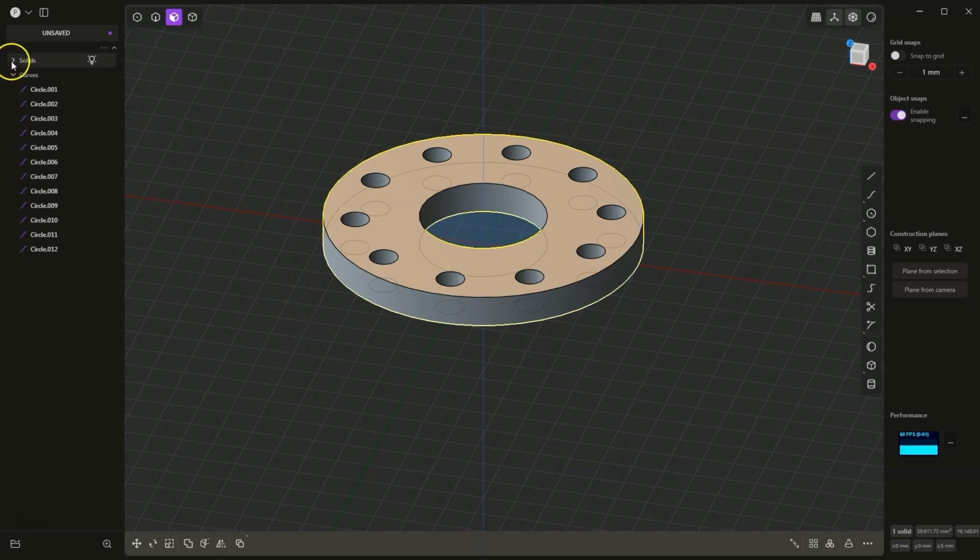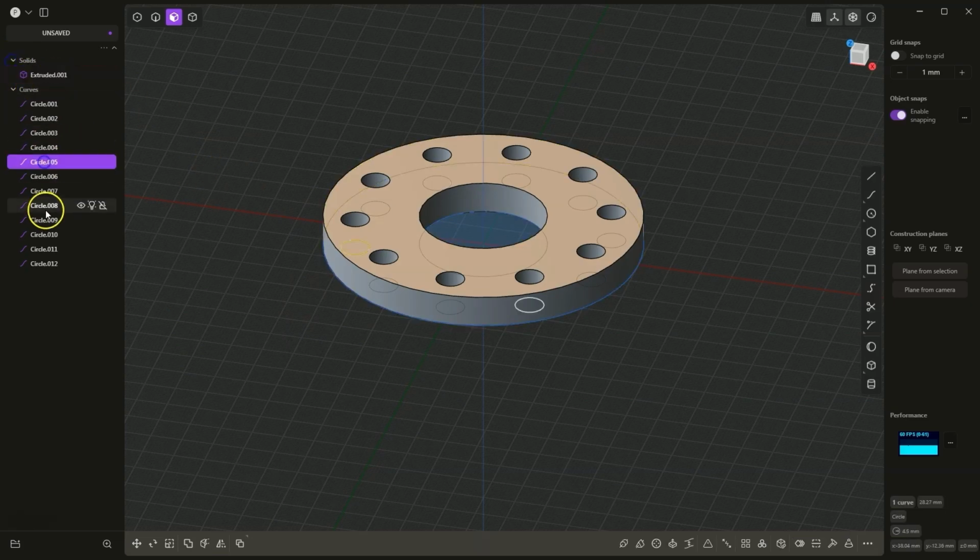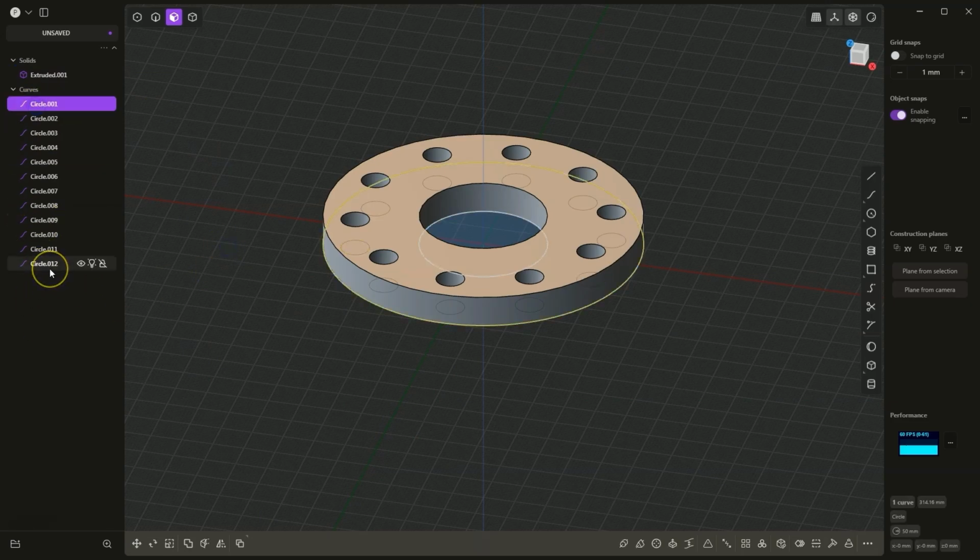A solid has formed here, and we have created a solid and flat geometries. As for these flat geometries, we can delete them because they will no longer be needed. When it comes to creating 3D models in Plasticity, if we create 3D models based on flat geometries, this model is not linked to those geometries. Once we create something, it stays that way. If we change some geometry, it will not affect the model.